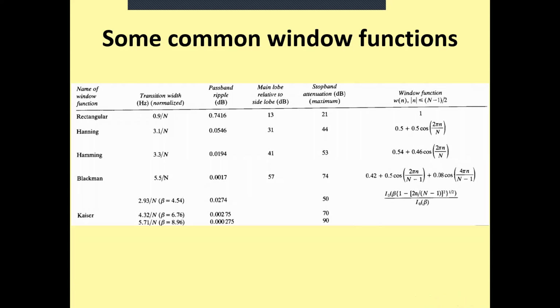So in this case, we are going to take the Hamming window or Blackman window or Kaiser window. Well, based on what? Based on the stop band attenuation. So we have some conditions we have to follow to determine the kind of the window, to select the suitable kind of window. We said that it is based on the problem requirement. Good.